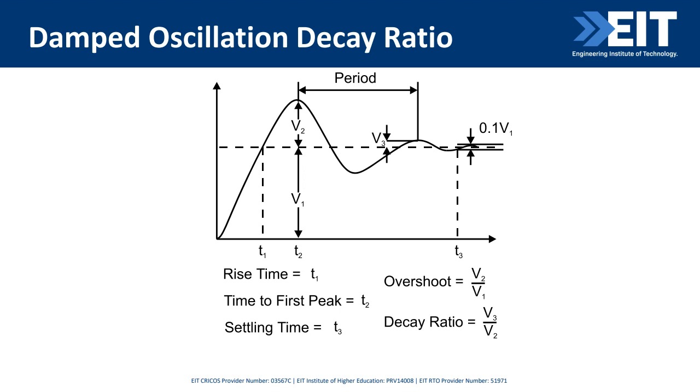So what we do is we go for a loop response looking like that. Can you see here, this guy here goes up. So this is the response of the process variable when I've made a step change. Goes up and then it drops down and then it settles. So this here is what we use to work out the tuning constants. With Ziegler-Nichols, what we're saying there is we get the loop to go like that, which obviously is not a good idea, as I said.